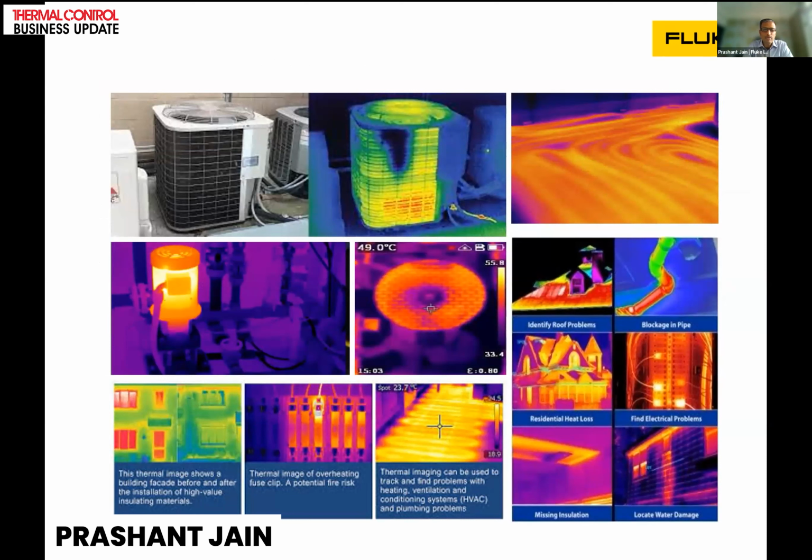Generally, when we are doing HVAC, we are dealing with either very cold or very hot substances. So this can help us understand if there is abnormal heating or cooling. We need to insulate our refrigerant lines. If the insulation is weak, we are losing our energy, we are losing our money. So it can help us find out if there is any duct which is choked, or any place where the insulation has gone bad and the hot or cold air is coming out of it.